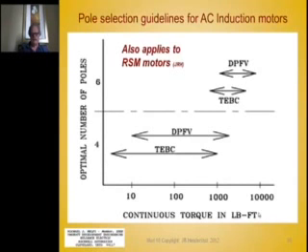But if you go up to 10,000 foot-pounds, you can use 6-pole or even 8-pole motors between 1,000 and 10,000 foot-pounds. That has to do with the fact that on those larger torque motors, the rotor is bigger, so the chord length is bigger. It's a matter of the leakage: the percentage of the pole flux that leaks to the next pole, the leakage reactance.